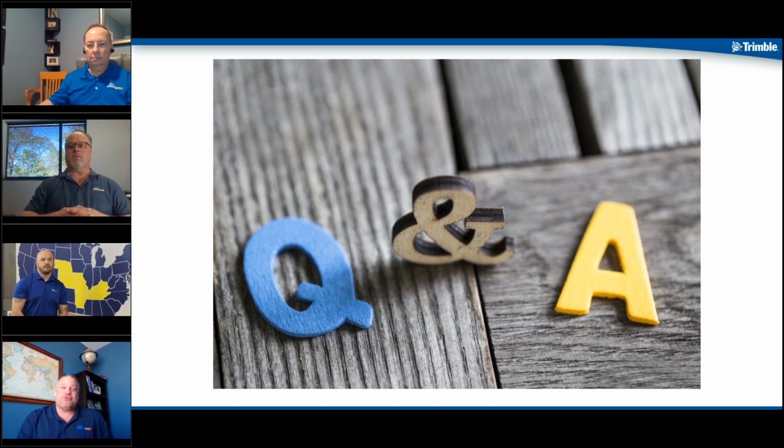To maintain control is a common theme across multiple projects, and I would start with things like making sure your robot's in perfect calibration. Do field calibrations. If you can't do it daily, do it weekly. If you can't do it weekly, do it monthly. But do those field calibrations. That will greatly increase your chances of maintaining higher accuracy control points.